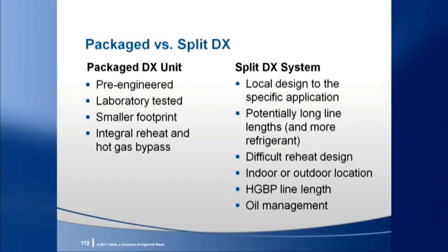There are advantages and disadvantages to either a packaged DX unit or a split DX system. The obvious advantage to a packaged product is that it's pre-engineered, whereas the split is typically a local design. A local design can be optimized for the specific application, but the packaged unit will be lab tested and its footprint is probably smaller if the split uses outdoor products.